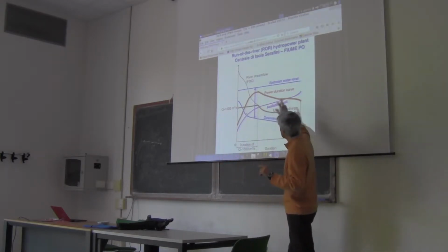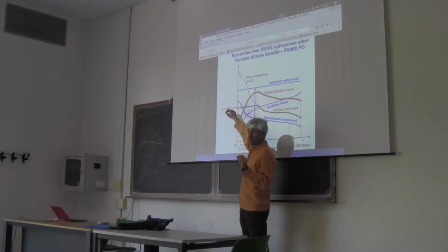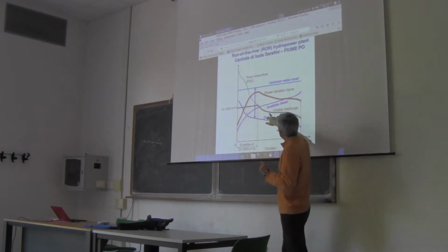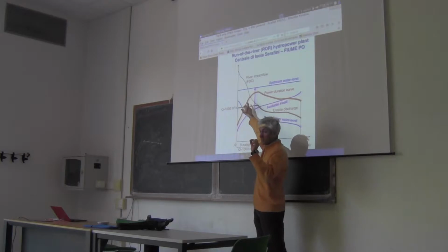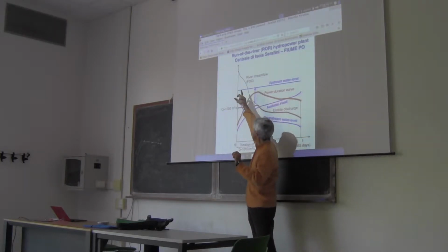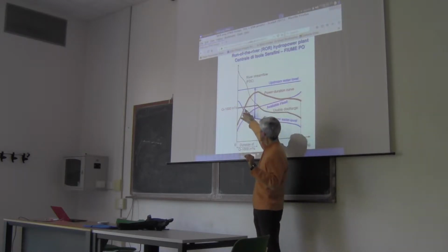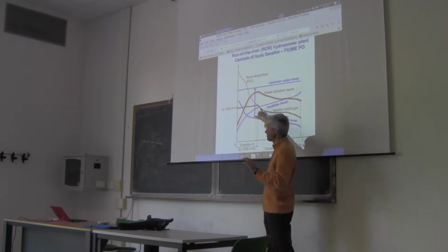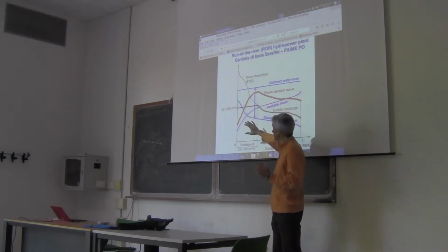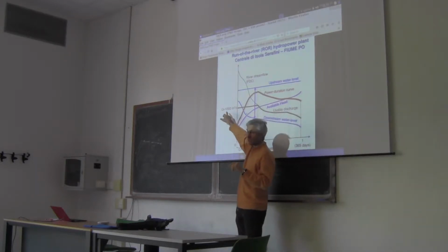Here you see that there is a flow duration curve. The thick line is the undisturbed flow duration curve, and the thin line is the original one. It starts from the max and goes to the mean. The thick one is the usable discharge, so it's the duration curve of the usable discharge. I think this should be clear. And the design flow is 1000.